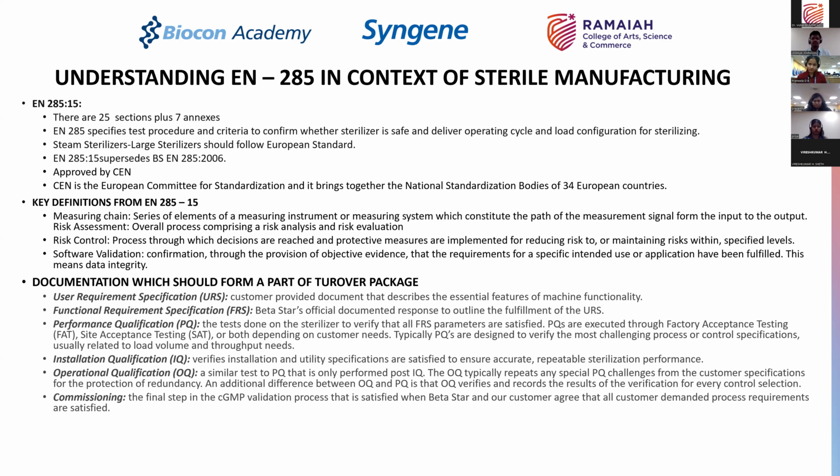So as a user, I have to provide what it is that I want the autoclave to deliver for me. I have to write what the essential features are, what size of autoclave I want, what type of load I'm going to put into it, how many autoclaving cycles a day I intend to run, and what the quality of steam is which I'm going to give to it. Sometimes there are geographies where it is not possible to generate steam through a separate source, and therefore I have to put in my URS that I don't have steam. Can you provide me a steam generator as a part of your own autoclave, for example?